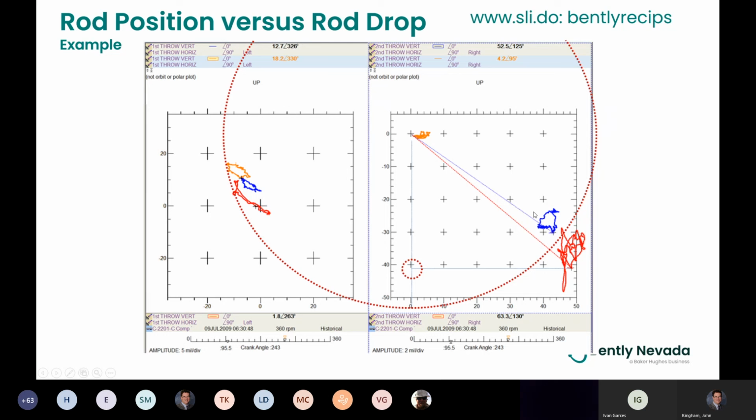So at any rate, a little bit longer, you see it really opens up and there's a lot of action going on. And it appears to be outside the clearance circle that we would expect. So you probably have some rider band wear going on here that's exceeded its clearances.